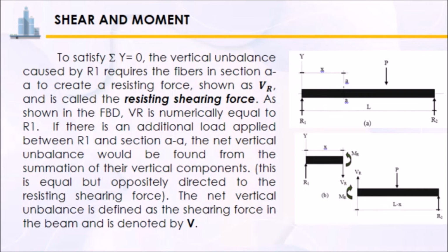So, medyo mahaba yun, pero sa madaling salita, sabi lang doon, walang horizontal force na ikinoconsider. Kasi, there is no horizontal load acting sa beam natin. And, gagamit tayo ng FBD, cut natin yung beam into segments, and para ma-solve ang shear is magsa-summation of forces vertical equals to 0 lang tayo sa bawat segment.